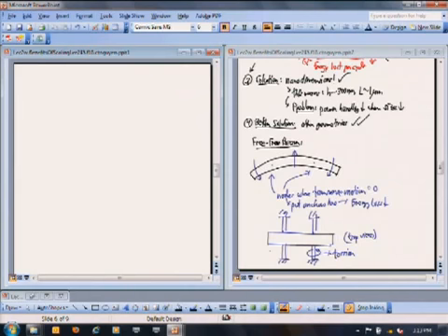Okay? What can you do to solve that problem in a circuit, in a transistor electronic domain? Not much. Right? You could use exotic technologies to lift that inductor above the substrate as much as you can. You can use exotic technologies, actually MEMS technologies, to turn that inductor around so its magnetic fields go this way and not into the substrate. Those actually work to increase Q to levels on the order of 40 to 80.